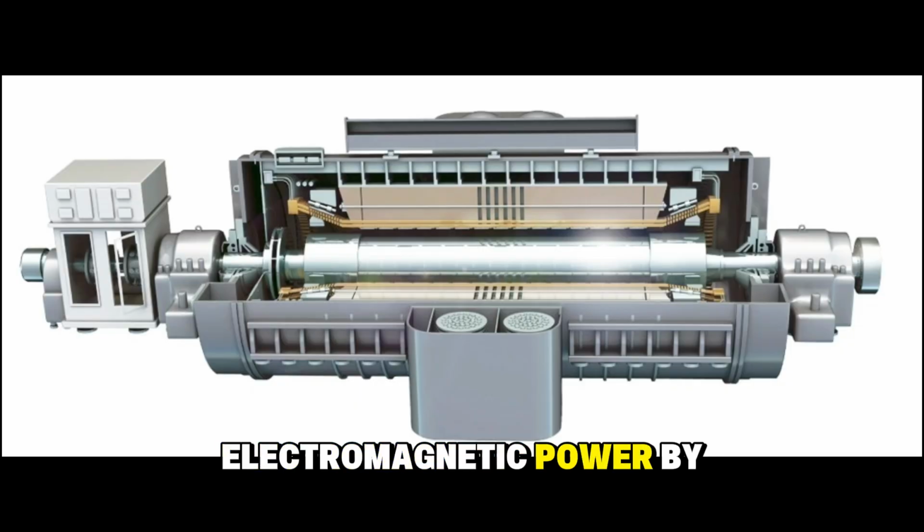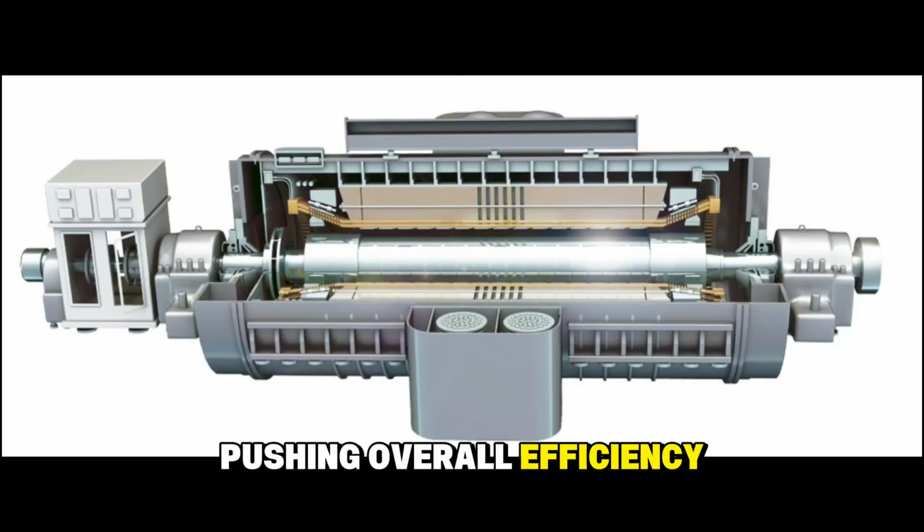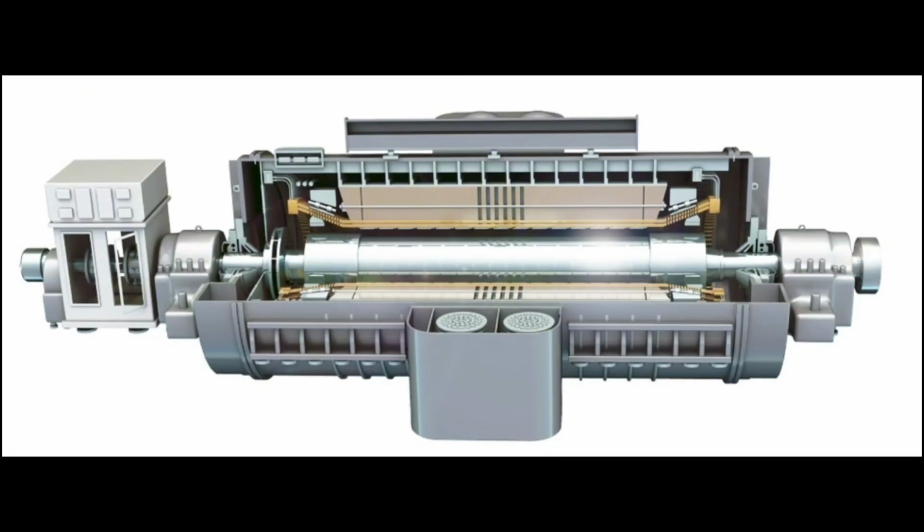To understand how this generator works, the turbine mechanical torque spins the internal rotor, which is an electromagnet powered by a DC excitation system. As this magnetic field rotates, it cuts through the stationary stator windings by Faraday's law of induction. This relative motion induces a high voltage three-phase alternating current (AC) in the stator. This electricity is then matched via grid synchronization and stepped up for transmission, pushing overall efficiency over 60%.